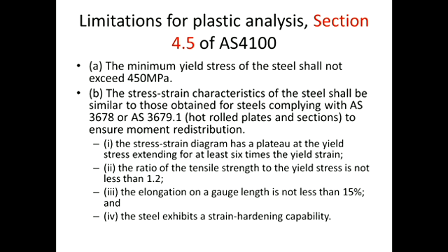So what would the elongation be indicating to us in terms of failure of the structure? So sorry. So where the plastic hinges might form. But this elongation on the gauge length is for us looking at a tensile coupon.